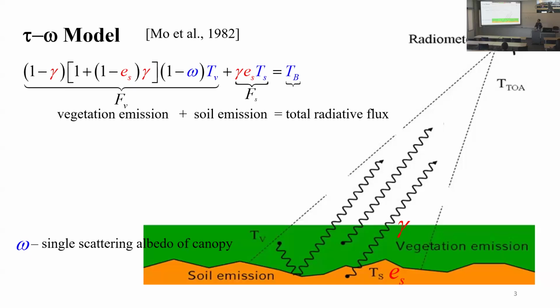The basic method of soil moisture retrieval from the satellite is represented by the so-called tau omega model. This is a simplified version of the radiative transfer method. Basically it says there is an emission of radiation. As we know, everything in the universe emits radiation at all frequencies. So the soil emits radiation, and we measure it at 1.4 gigahertz and the narrow band around it, so we can receive enough signal for data analysis. This is the soil emitted radiation.